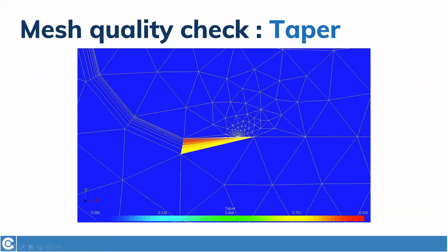After noticing an increasing number of mesh-related problems which occurred due to faulty viscous layers elements, we decided to implement a new mesh quality check, which checks the so-called taper parameter. Taper mesh quality check represents the area ratio between two triangles separated by a diagonal within a quadrilateral face. This check helps to even easier detect the possible problem in the mesh, and it helps to correct the faulty mesh even faster than before.